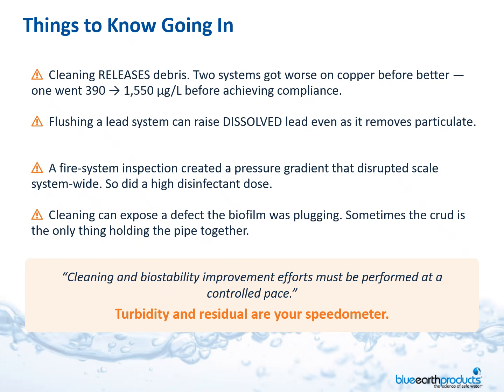But there are a few things that you need to know going in before you start a hygiene program on a building that is struggling. And that is, when you are cleaning, you're releasing debris. And it is very likely that the problem is going to get worse before it gets better. And flushing a system with lead can also increase the dissolved lead, even though you're removing the particulate lead from the system. And any kind of disruption that you have in flow or in treatment will also affect the chemical scales in the biofilm, causing possible upsets as well.